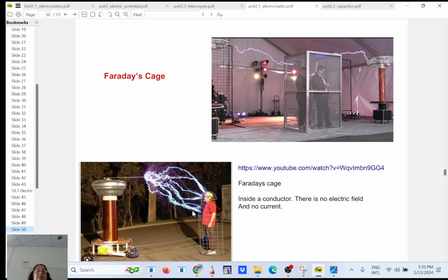So you see the electric field here because the cage is connected to the ground. If this is positive here, you see electric field wants to go from plus to the ground. So you visualize the electric field. The voltage is so large, thousands of volts, that it will be enough to have a breakdown. You have a discharge, and the charge wants to go to the ground. Is he safe inside? Yes, because the electric field cannot penetrate inside the cage. Okay, it's called the Faraday cage.